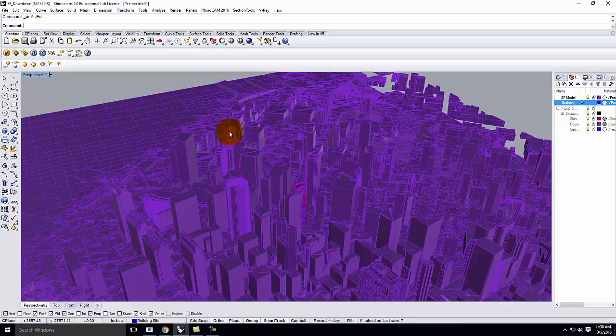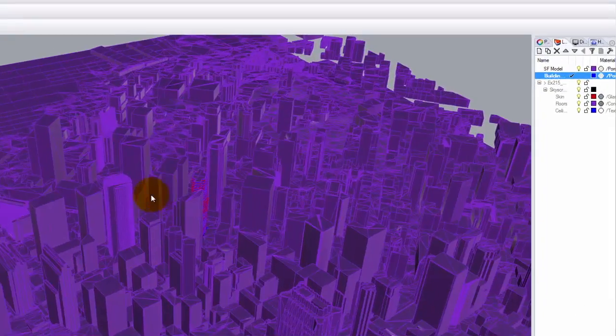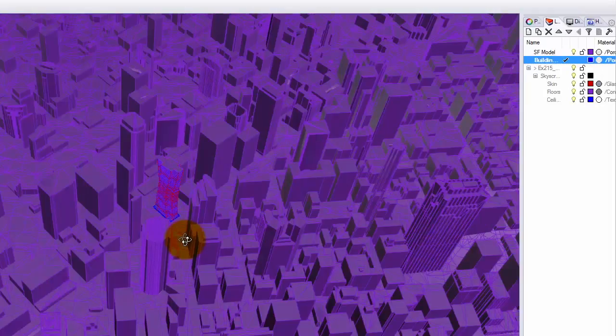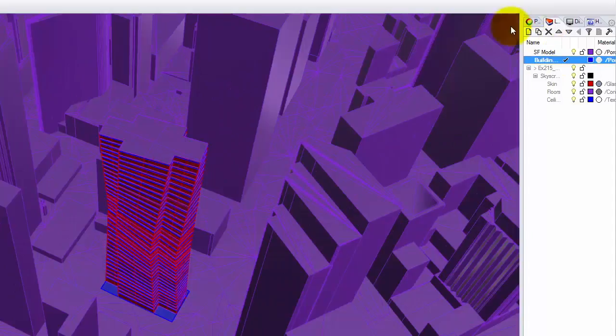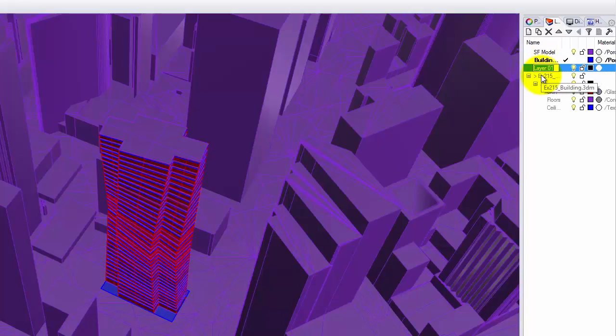I'm going to skip forward and go to part 3, and I'm going to follow VRay 8.17, which is the sun, to establish the sun into the scene. Let me zoom in here a little bit. So I see my building. I'll start with creating a layer, and I'm going to call that layer environment. You don't have to have this set up as layers, but it's going to make your life easier long term if you get in the habit of establishing layers. So I have an environment layer. I have a sub-layer for environment called sun. And I'm going to create my sun and put it on the sun layer.